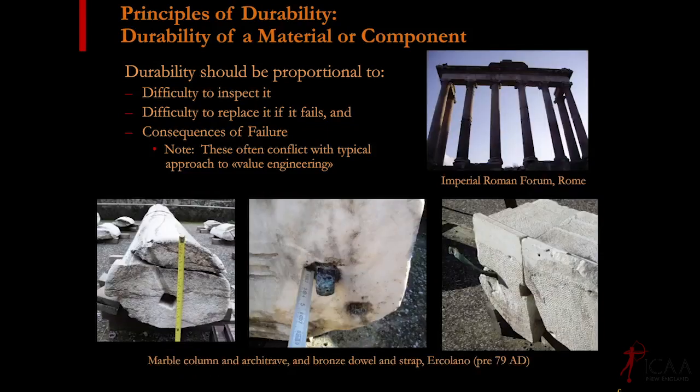Now, here in the Imperial Roman Forum, the Roman connections of stone to stone, these were not just mortar that was laid stone on top of stone like we would do today. These were actually typically dry joints, no mortar between them, connected with bronze dowels. And then the bronze dowels were sealed in lead, and this is a little lead channel that runs out so the excess lead can flow out the surface. And that was pretty typical. That's how the Colosseum stonework was built, and that's how a lot of these were built.